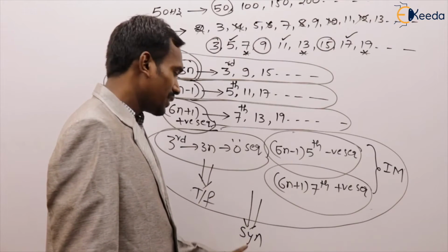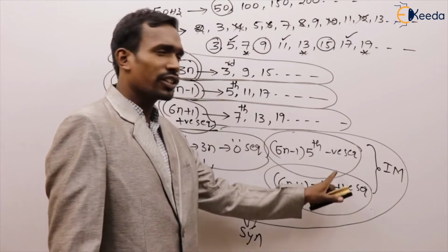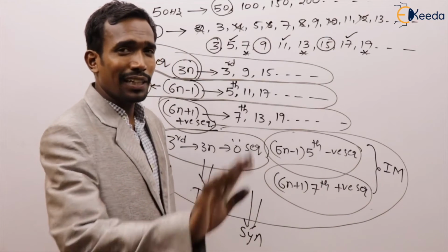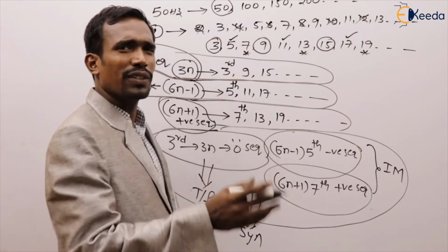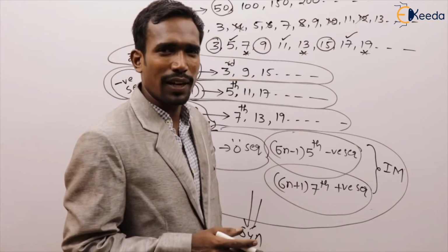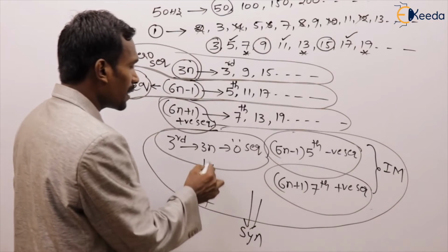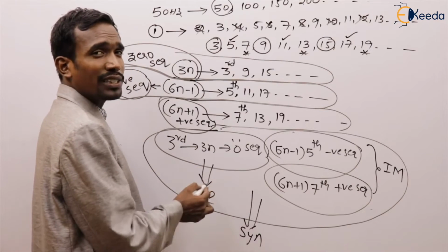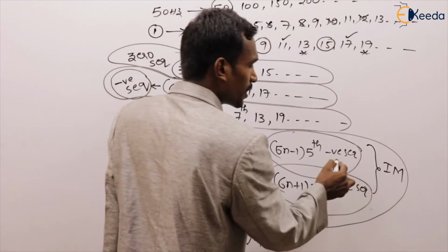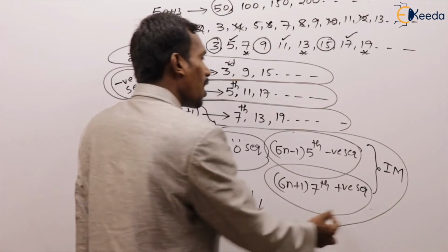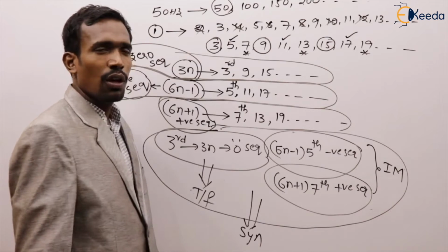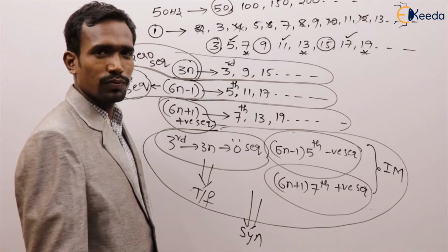EMF is there in a synchronous machine and rotation is there in a synchronous machine, but there is no rotation in a transformer. Generally the EMF of the induction machine is not required. So in a transformer, triple-N harmonics are the most effective harmonics. In an induction machine, fifth and seventh harmonics are most effective. In a synchronous machine, all the harmonics are most effective.